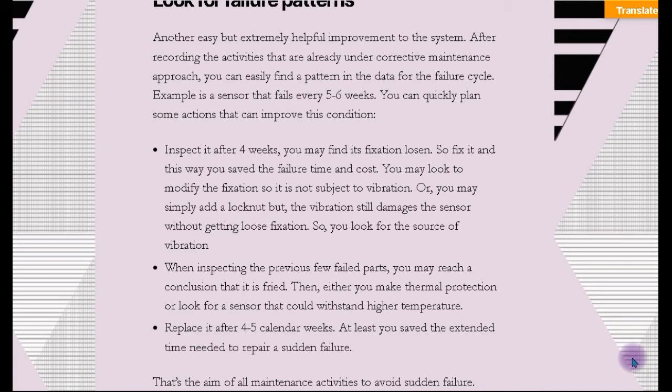It's only for one sensor, but I tell you, the cost of this one sensor is not only in the cost of the sensor. That we will come to in the next point. Maybe after inspection of the parts itself that you have in hand, after a few failures or something like that, you will find that the sensor is fried. It's subject to more heat than it can withstand. So maybe you put some heat shield or you change it to a higher rating for withstanding the higher temperatures, and so on and so on and so on.